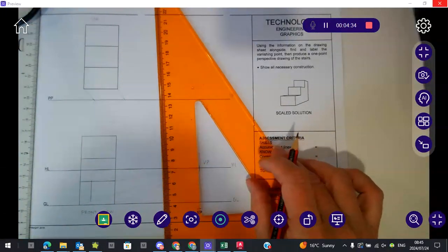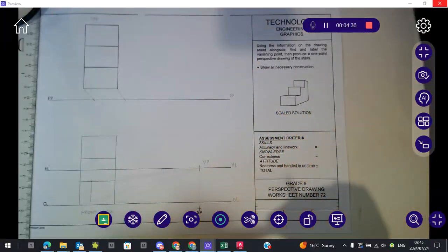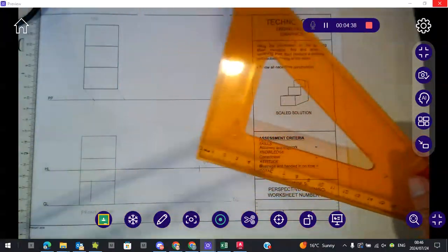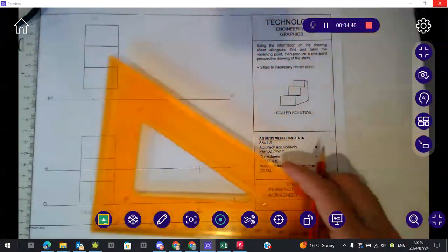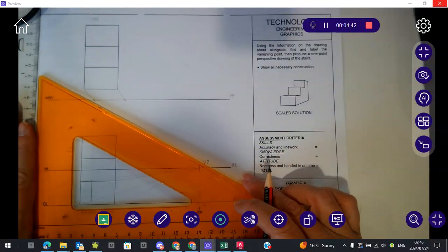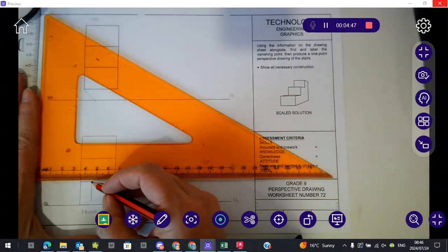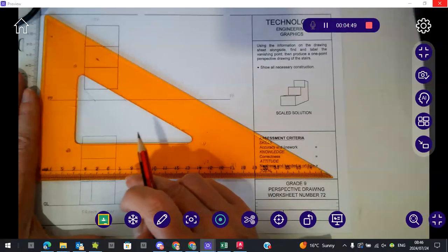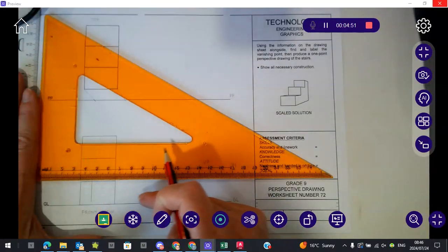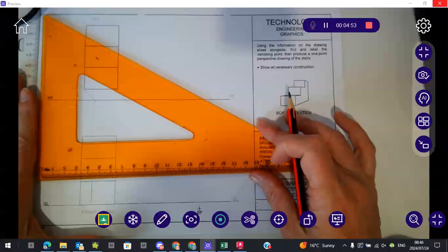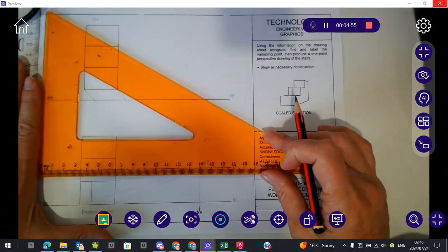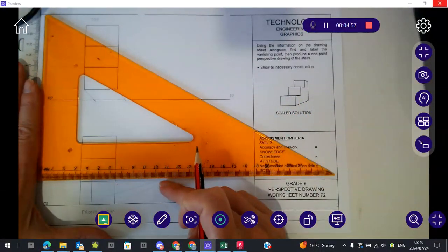Now, you will be able to take your set square, and I'm going to lean my set square against the edge of the clipboard and draw this line parallel. Okay, so that's going to give you those perfectly parallel lines. So lean your set square like this against that clipboard and get a nice horizontal line.